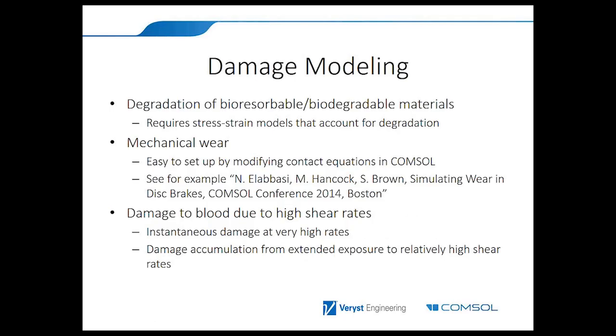Biodegradable materials, like biodegradable stents or sutures and stuff like that, degrade intentionally in the body, and to capture that degradation, you need advanced stress-strain material models. Another point is mechanical wear, for orthopedics especially. It's relatively easy to modify the contact equations in COMSOL to account for wear, and we did that in the paper that we presented in 2014 at the COMSOL conference, using disc brakes as an example, but it can apply to any wear phenomena.